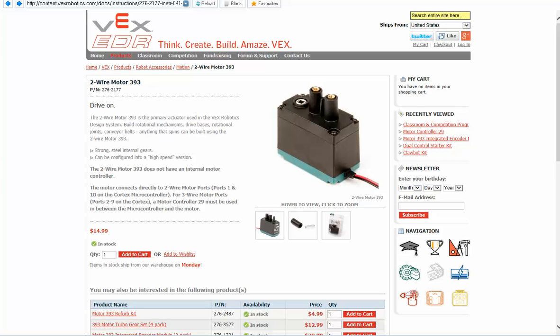But you need to open the motor, step 2, take the shafts out, take the gears off, install the new middle high-speed gears, and just reverse the process and seal the motor again. Like I said, every part has something of that nature.